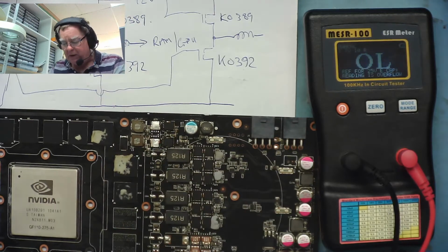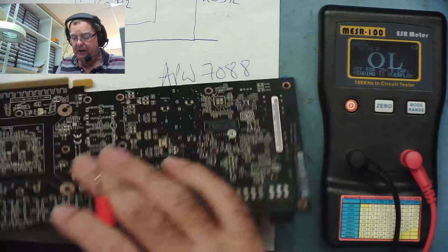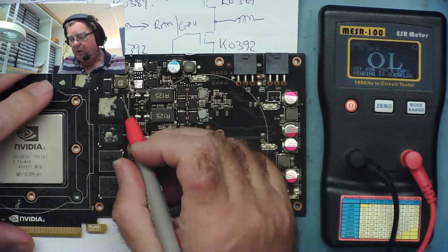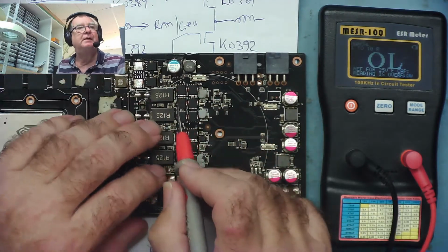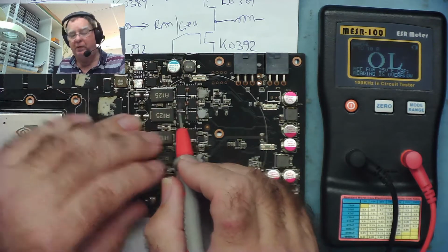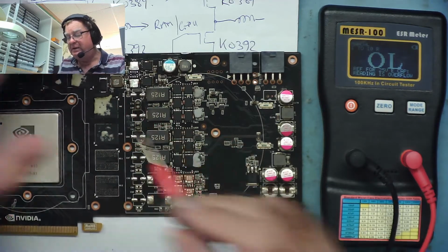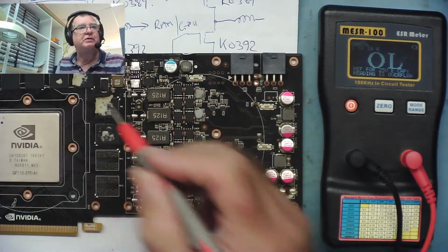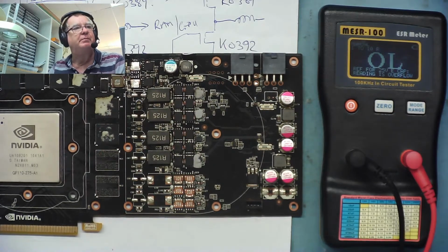So I think what's fooling us here, or fooled me, is the fact there's a lot of capacitors to ground on this side, and there'll be some capacitors no doubt on the other side. And I think what I'm effectively seeing is a path to ground through capacitors on this side, and a path to ground through capacitors on that side. Obviously some is going through the coil, but that has a resistance of 1 point odd ohms, and I think that's what's jinxing it. The fact I'm not seeing the resistance of that plus the capacitance on the ESR meter. So that was the first thing that bothered me.